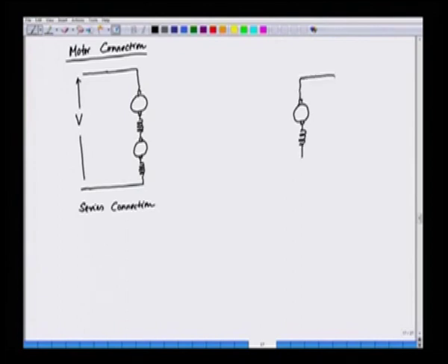So, these are the traction motors, they could be connected in parallel because we have multiple motors. So, we apply some voltage here. This is V1 and this is V2. Of course, the voltage will be different here because the series voltage will be higher than the parallel voltage, and here we have the parallel connection.